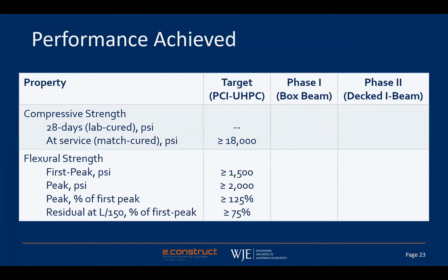All right, so during all of this production, the material's properties were carefully monitored. Tests of the compressive strength were done based on lab curing and on match curing, where we see the benefits of the internal heat of hydration on the compressive strength. So these are the results compared against the 18,000 PSI target. Certainly we have far exceeded those.